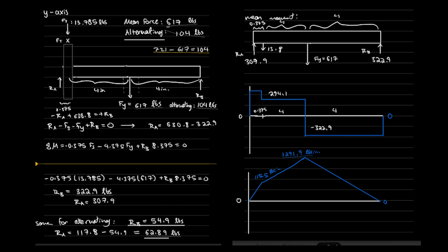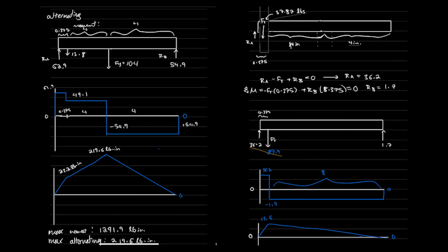Calculating the radial and thrust forces combined with buoy arm force allowed us to determine the reaction forces at the bearings in both the Y and Z axes. This approach enabled us to identify the maximum moments for mean and alternating forces in the Y plane. Additionally, we assessed the Z-axis for separation force-induced moments, resulting in a negligible value that wouldn't contribute significantly to the mean moment.